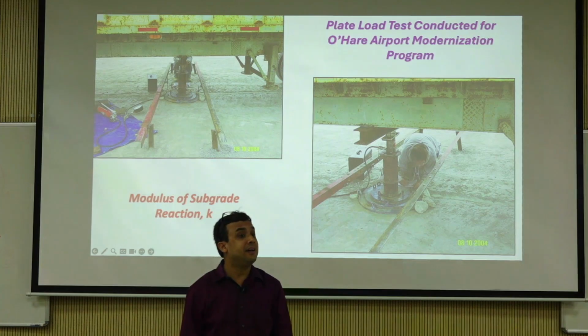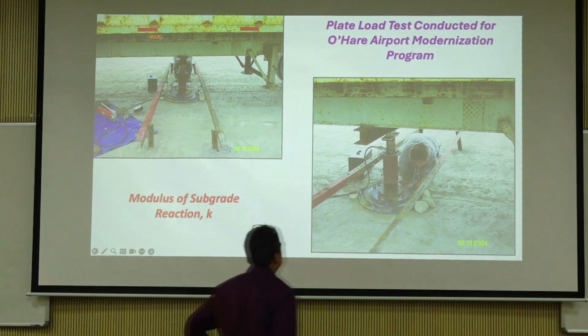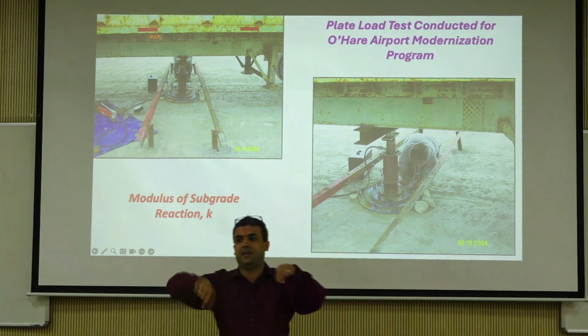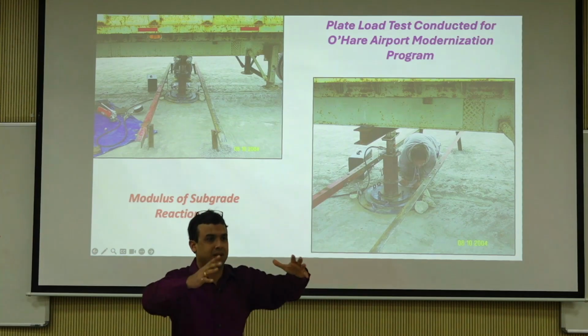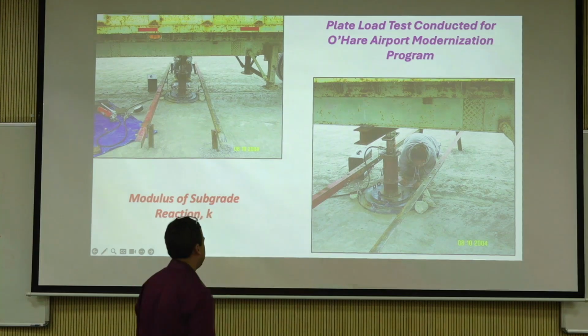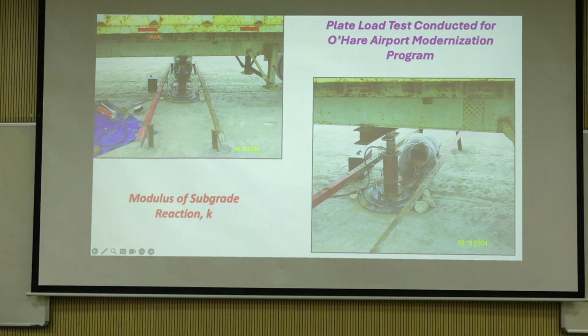Say it again. It's related. You are actually trying to avoid bending of the plates because we are trying to measure the deflections at the circumference, right? So the plate actually sometimes bends as well. So if you make it thicker, the bending stiffness actually increases. So it's actually to avoid errors.